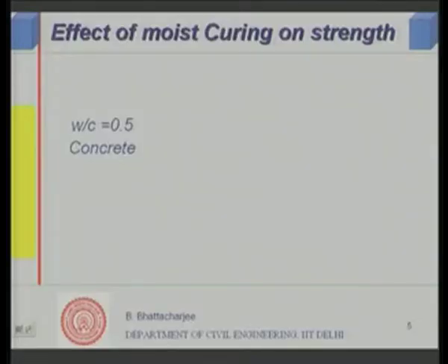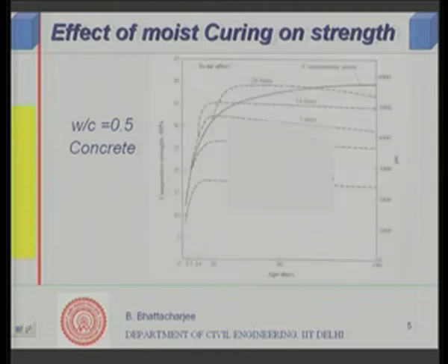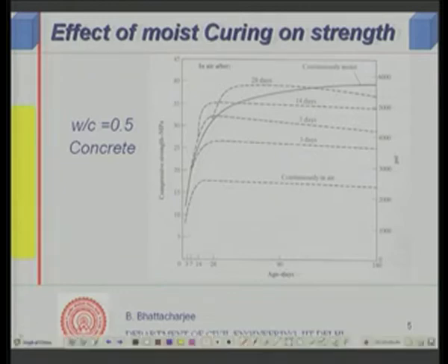Right. So, let us see diagrammatically what happens with this strength development issue. Past experiments have shown that the strength development of concrete takes place in this manner. If you keep it continuously in air, this is the curve. This side is the compressive strength of concrete in MPa, this is the same thing in PSI, and this is the age. With age you see the strength of concrete increases, but if you do not replenish the water, the strength does not increase beyond a point; in fact, it will have a slight decrease.